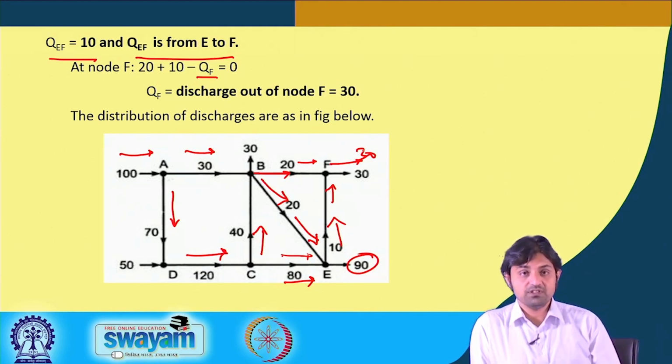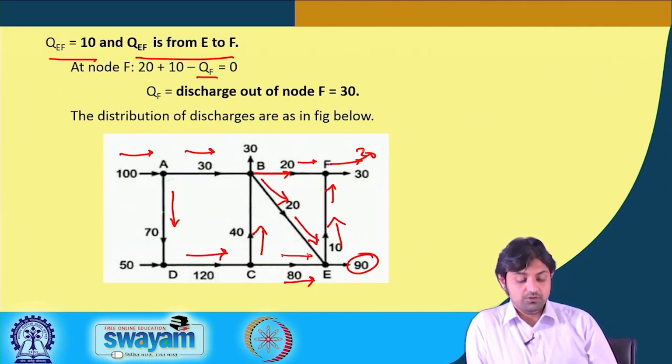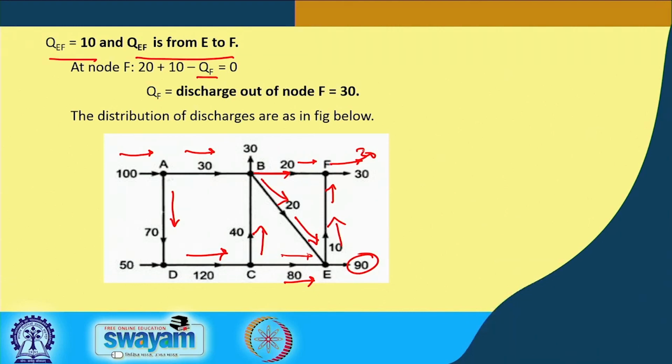So this is one of the simplest problems that you can see about the equation of continuity. Normally this could also happen that in place of the discharges, only the velocities are given, and the areas of these pipes could be different, but the procedure will remain the same. You have to calculate A1 V1, A2 V2 and so on, and equate the discharges as we did here in this simplest example. So this is for today.